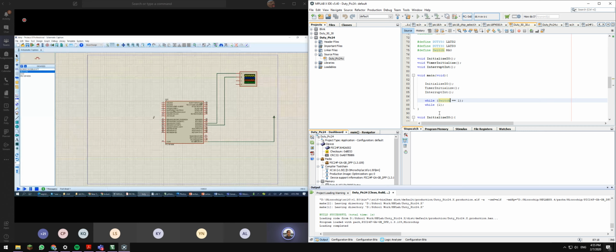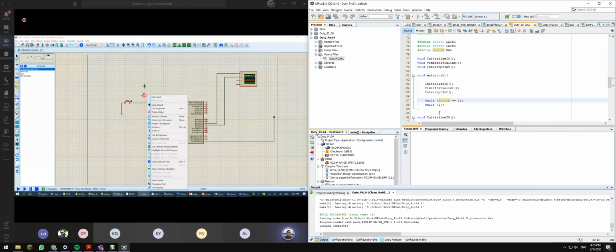So we pull out the buttons. This one you link over here. We take out the ground. Then we give it a power, not pulled to high. We put the LED and the resistor, so link the resistor. So you pull it to high.